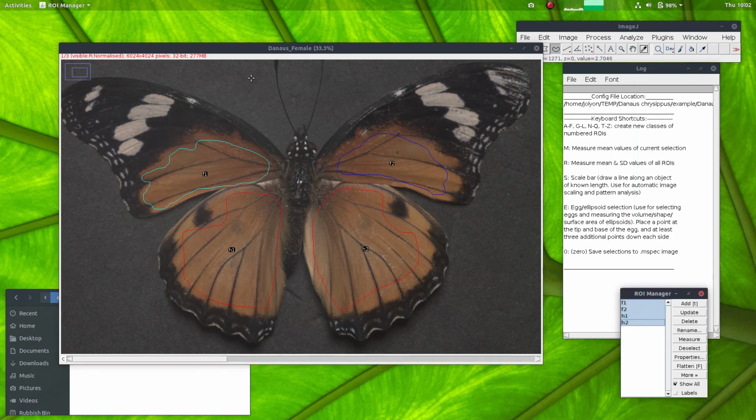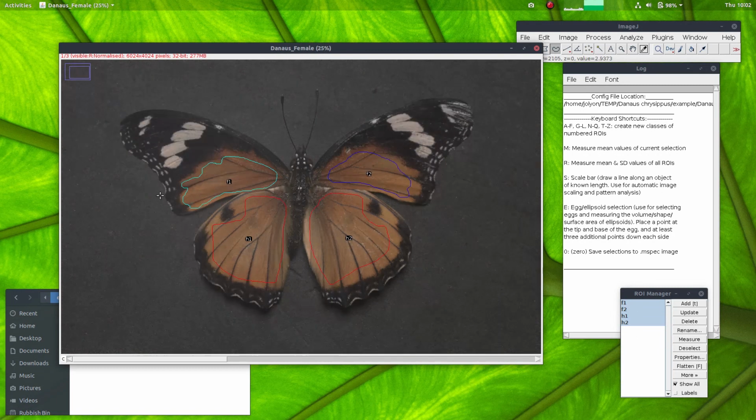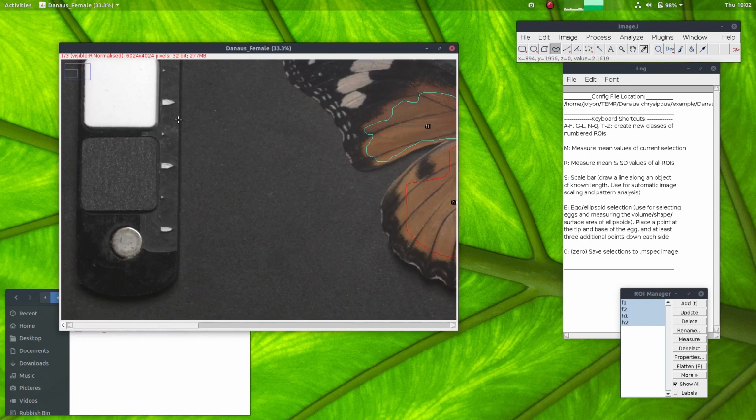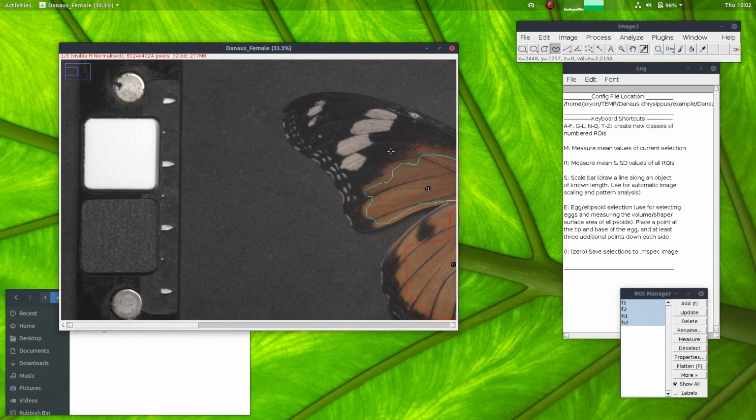Here you'll see the 4 different regions of interest that we've created. Many different functions in the toolbox, for example the QCPA framework, require a scale bar to be used. So when we're using a scale bar, we can just select it at this stage, draw a line anywhere in the image that you know the distance of. So I know that this is a distance of 30 millimeters.